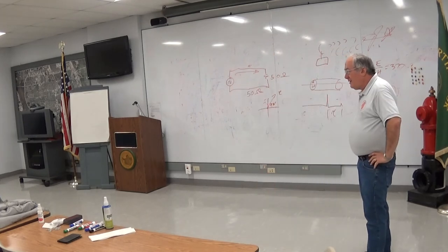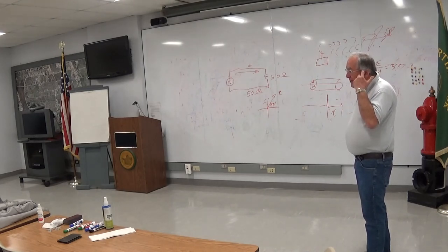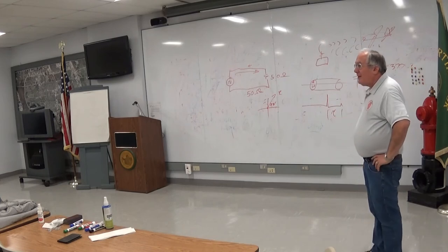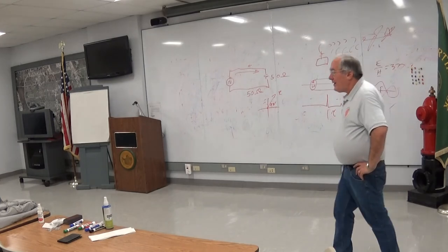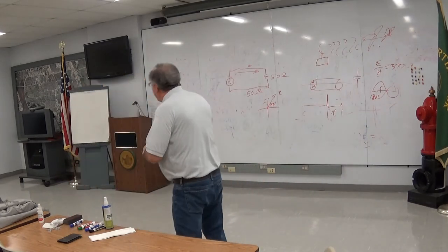Half a wavelength. A quarter wave, which is your ground, which is a half plane, so you got the wavelength but it's half, split between the counterpoise and the actual radiating element. Okay, there's a reason for that. That's actually 2 quarter wave elements stacked.